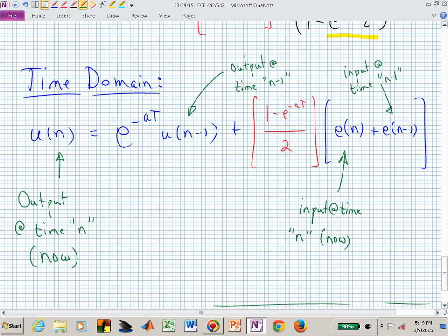And you just keep doing that. You'll have to have some storage, some memory locations, but that can be done. You just pull up those particular values, add them together, scale it, and add them to the previous output and generate the current output. And that's low-pass filtering this signal that's coming in at E.